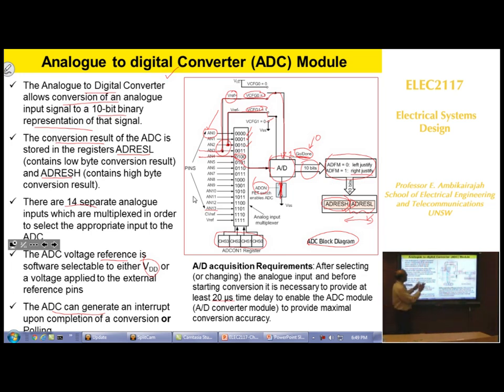So anyway, in this slide, all we are saying is that we can program the ADC the way we want it. There are 14 channels available. We can pick and choose the channel you want, and also you can decide what sort of voltage swing you want. You can decide whether you want to measure just a single voltage or differences between voltages.